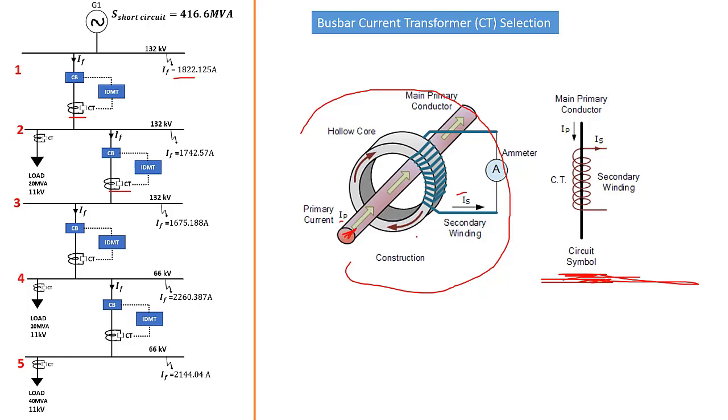Now, according to the process of transforming the current, this is the same process as normal transformers work, like a voltage transformer, working on the phenomenon of electromagnetic induction. According to Ampere's law, together with Maxwell's equations, if a magnetic field is integrated around a closed loop of wire, the value of that integral is equal to the net current enclosed by the loop of the current transformer.